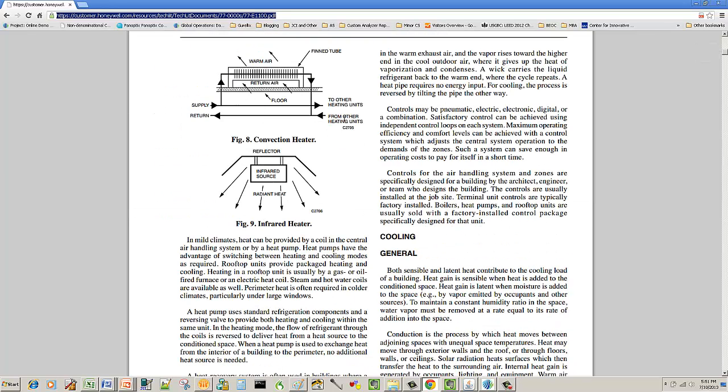Here we're seeing some convection. We're also seeing radiant. Now, convection heaters, we've all seen them. Traditionally, you'll see them in commercial office space and government buildings, lining windows. You see this more so up north than you do down south. This has a common loop, and it feeds through here. Typically, you'll have a wax valve, and that wax valve will let the actual flow go through. Sometimes you'll have an actual control valve, and that'll be linked to a common thermostat.